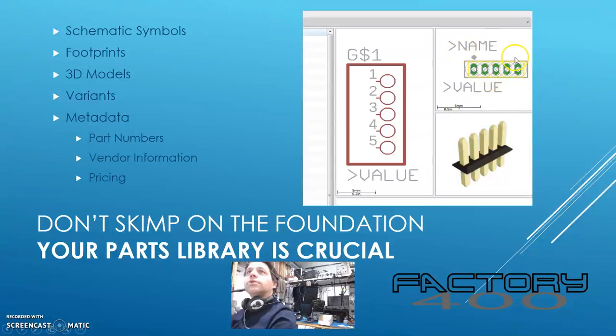And this is the actual definition right here of how your circuit board will be physically laid out. This is going to include information that your circuit board house will need to make the circuit board, including, in this particular case, drilled holes, and there's a little dot right here which depicts pin 1, so that when you physically get your board, you can see this little dot and know which pin is which. And that so far is pretty simple.